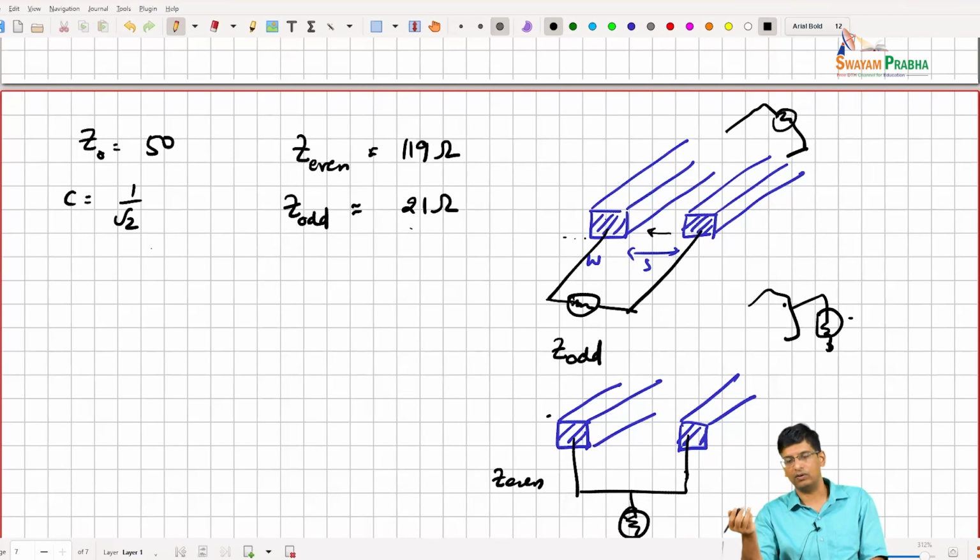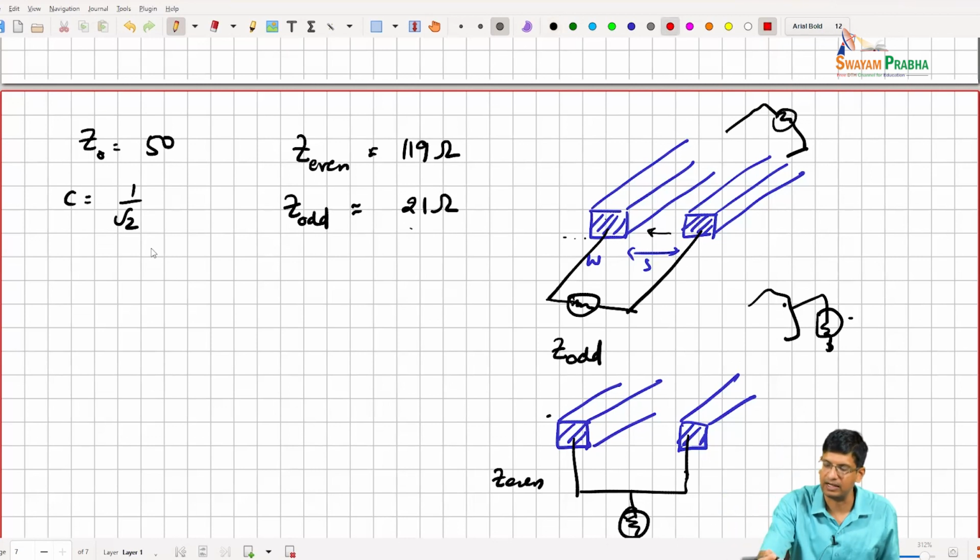And then, it's also just similar to the vertical natural capacitor approach of trying to do tight coupling between different fingers in order to get high capacitances. You have degrees of freedom. You can be creative, right? You can have multiple, so you can connect from here to here and have another parallel edge of this, right?